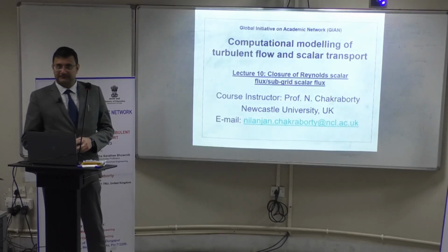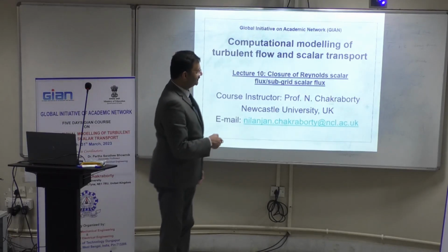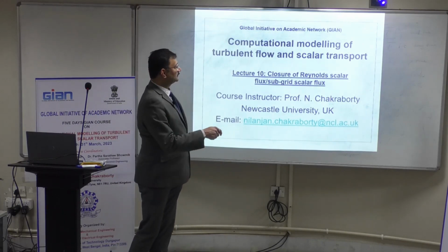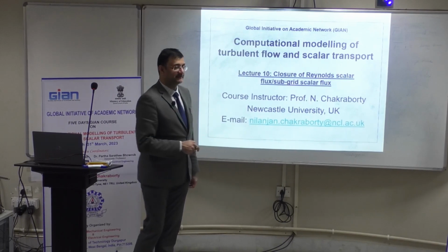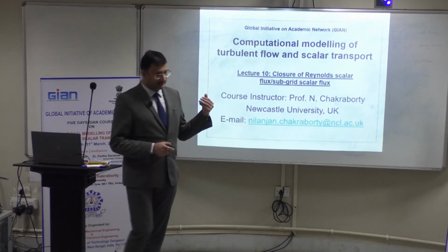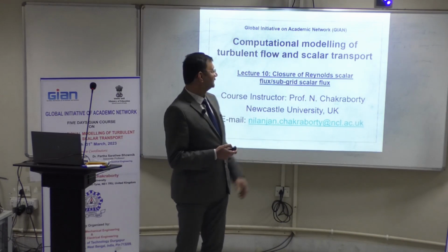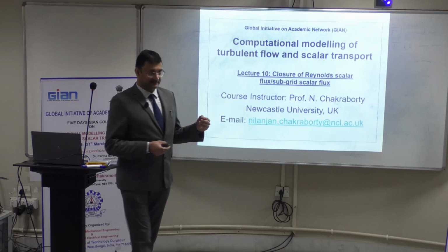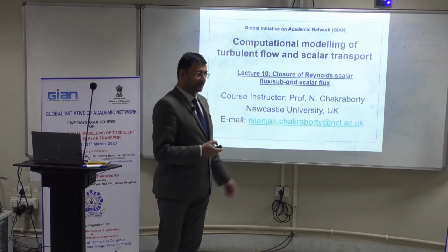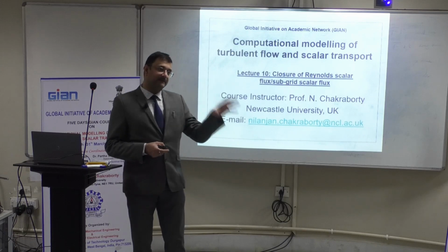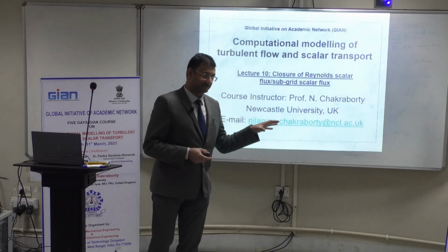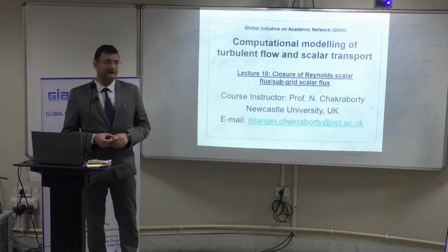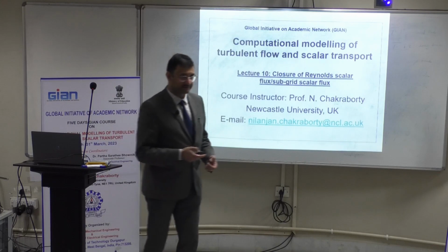Last lecture today, we are going to focus on the modeling of scalar flux. First we'll talk about closure of Reynolds scalar flux, and then we'll go into the LES context and the closure of subgrid scalar flux. We have already talked about scalar flux a little bit in the previous lectures, but this lecture will primarily focus on the scalar flux closure, and you will need that if you are actually solving for the energy equation or if you are solving for any mass fraction equation.